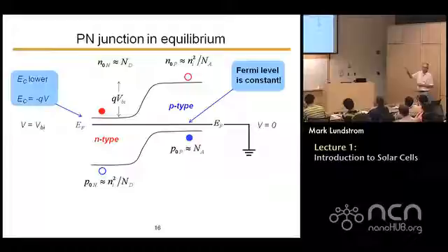What you argue is that what the voltmeter really measures is the difference in Fermi levels. It doesn't measure the difference in the electrostatic potential. What it really measures is the difference in the Fermi energies. And in some cases, those are the same things. But when you have junctions and you have built-in voltages in equilibrium, they're not the same thing.